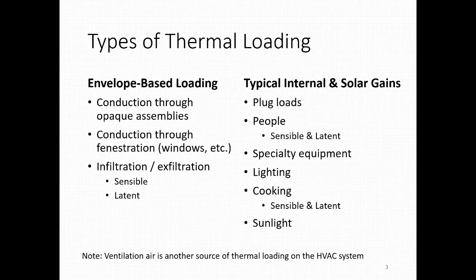The sun comes through your windows and heats up materials inside of the building, like concrete, for example, and that energy will be re-emitted later. So a lot of the time you have those delayed gains that later turn into loads.